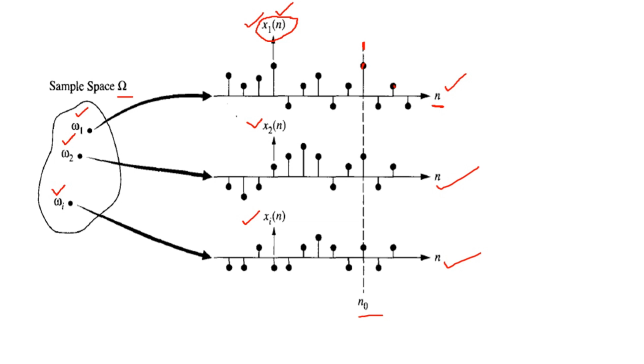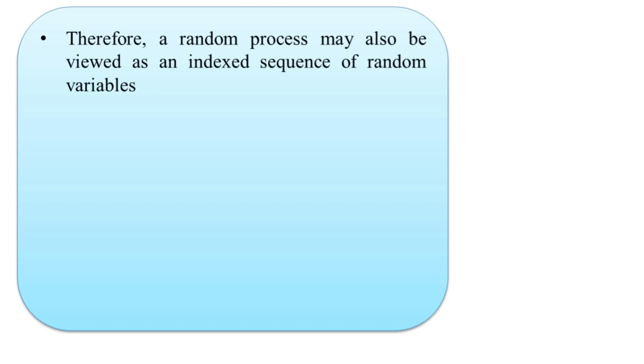Now there it is, the representation of this discrete time random process in the mathematical way. Therefore a random process is nothing but the indexed sequence of random variables as shown in this particular diagram, and mathematically the sequence can be written very simply. Here we have the double-sided sequence. In this particular representation, you can take x of 0 to be the central element.